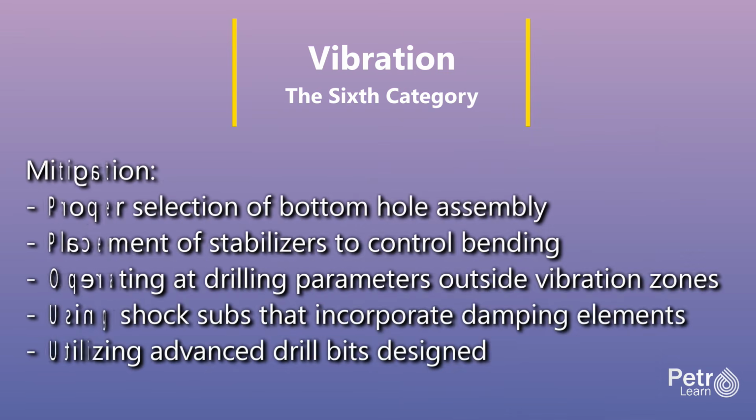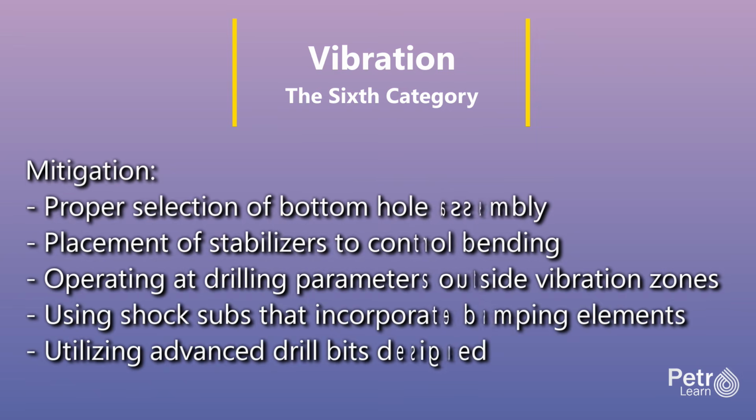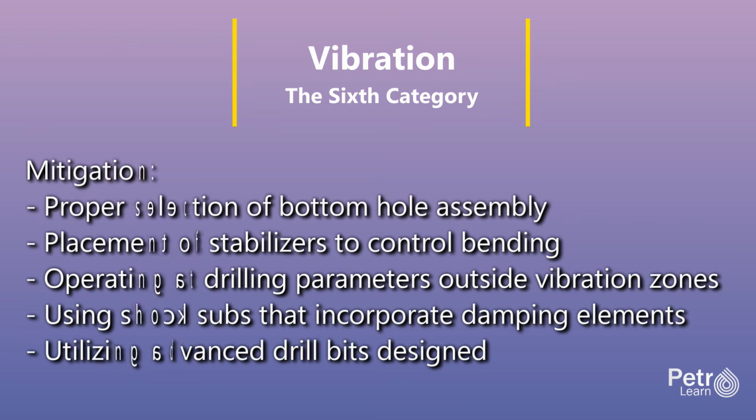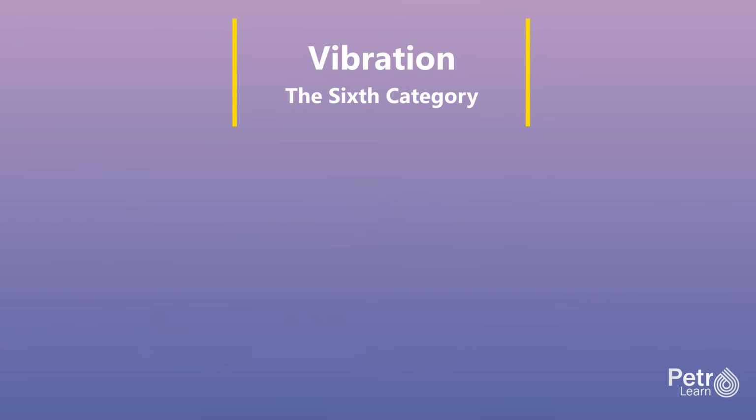Mitigation of vibration involves selecting bottom hole assembly designs with proper placement of stabilizers to control bending, operating at drilling parameters outside the vibration zones, using shock subs that incorporate damping elements, and utilizing advanced drill bits designed to operate smoothly in specific formations. Modern rigs with high-frequency data acquisition can detect vibration patterns in real time and alert the driller to adjust parameters before damage occurs. The driller changes weight on bit, rotary speed, or flow rate to find a combination that drills smoothly.